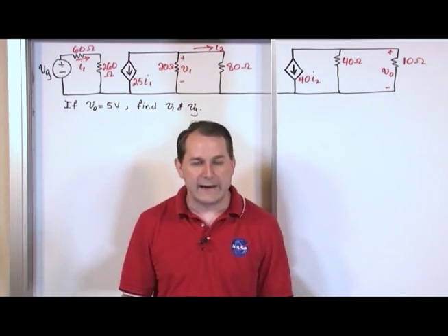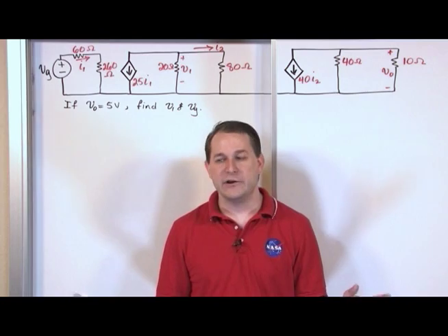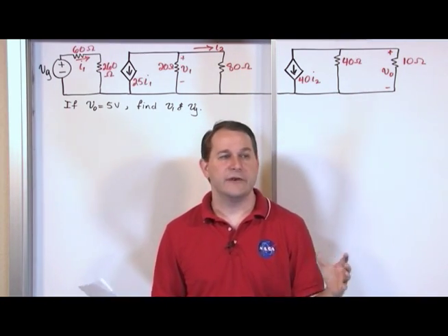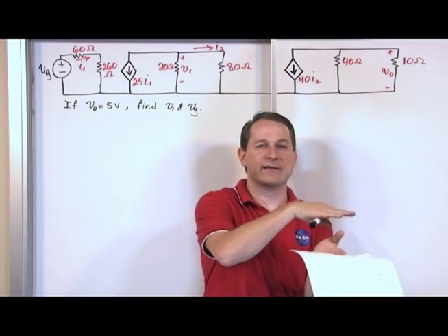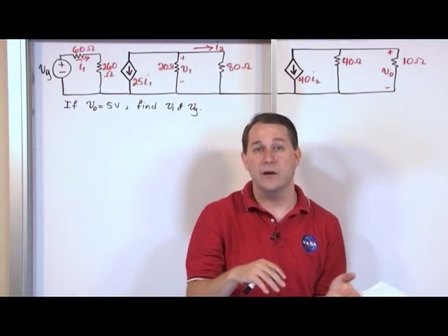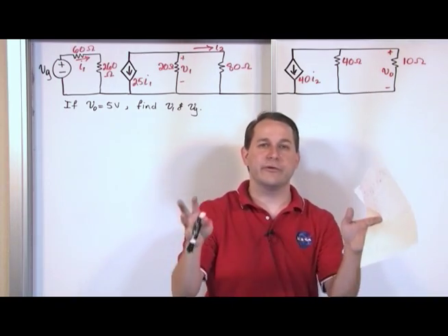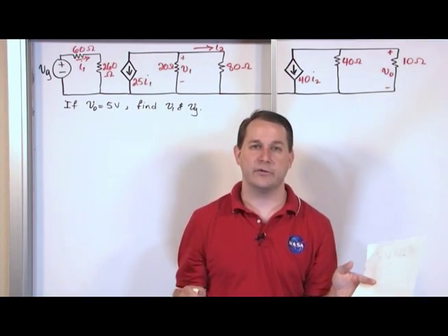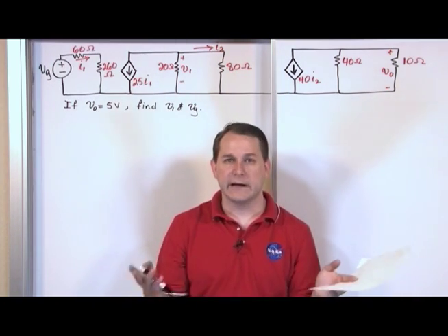I'm getting a little ahead of myself, but if you don't have a common voltage reference, and you just let everything float around, then you get really big problems, because you might have one circuit over here whose low voltage level may not be 0 volts. Its low voltage level may be something else, and it's floating around. It's not tied to anything. So you can get these dangerous voltage changes between different circuit elements if they're not tied down to a common point. It can actually cause arcing and melting and things like that.